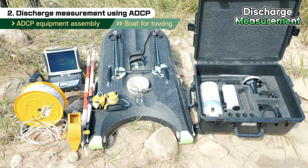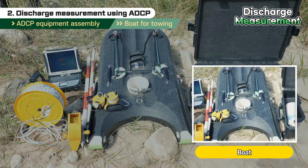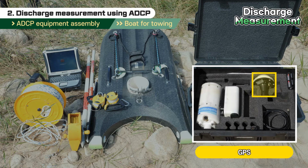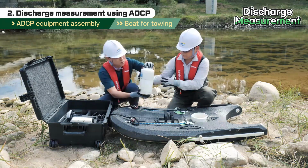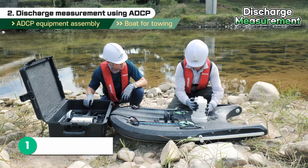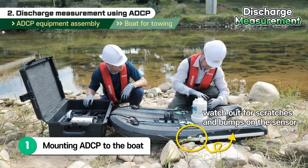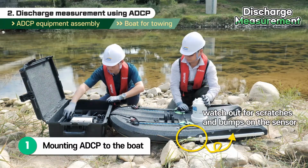The discharge measurement equipment using a boat for towing is composed of a boat, sensor, communication box, GPS, and laptop. We assemble the ADCP equipment ourselves. We install the ADCP on the back part of the boat and pin it so that it does not move around. Since the sensor protrudes under the boat, the on-site worker should be careful not to scratch or bump it.